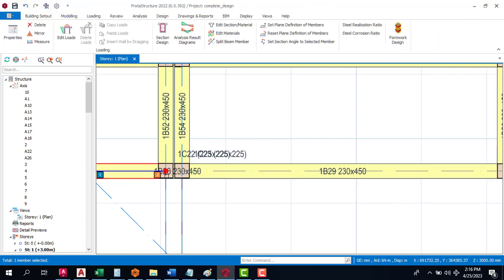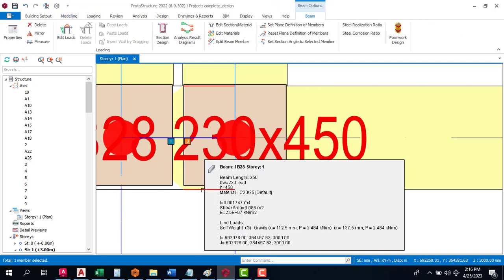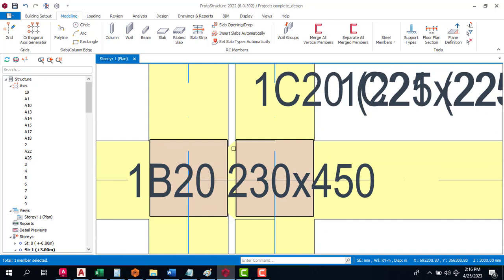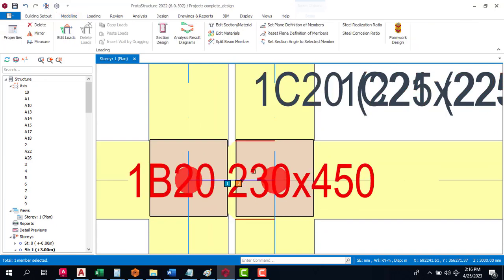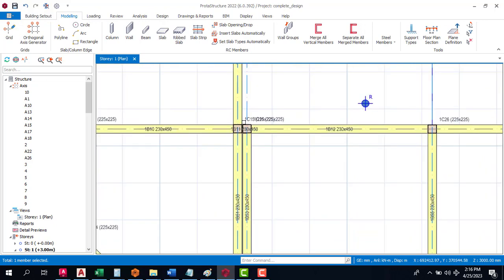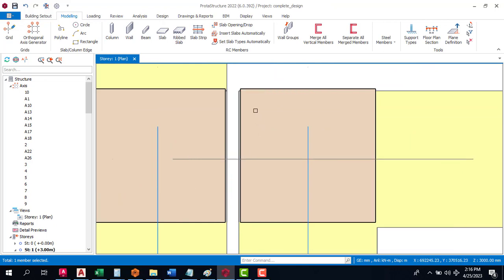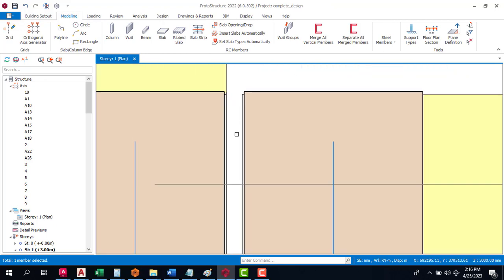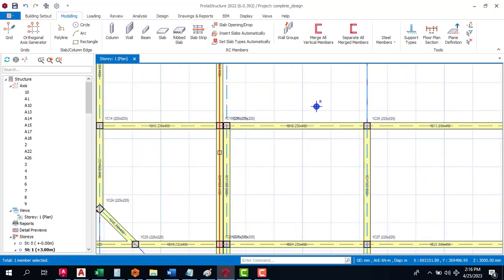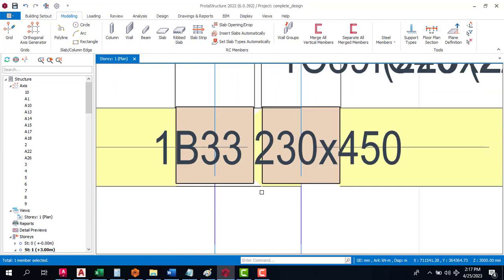But you see there is a little... I think there is a small beam here which is not supposed to be there. There's another very small beam here which is not supposed to be here as well. So the buildings are supposed to be completely separate from each other, but very, very close to each other, without anybody noticing that you have two different buildings very close to each other. That's in essence what an expansion joint is, okay?